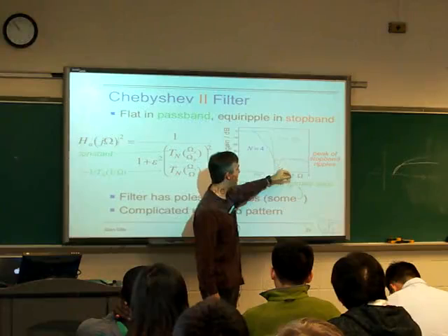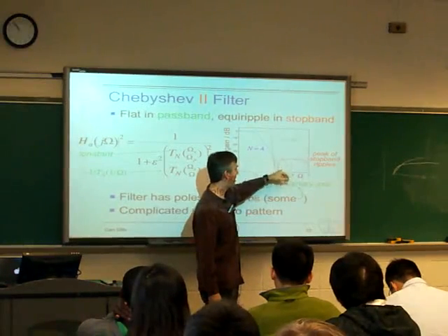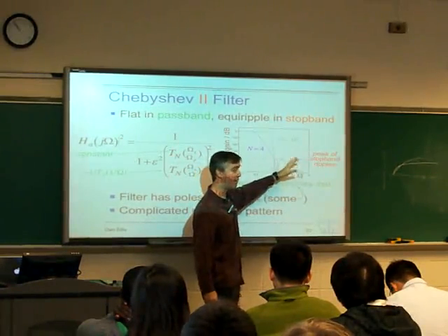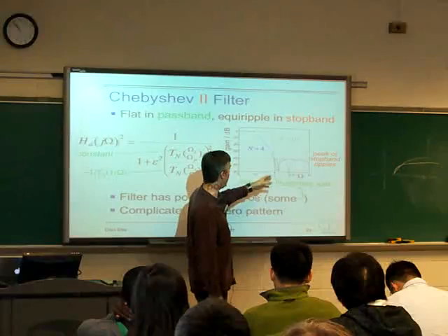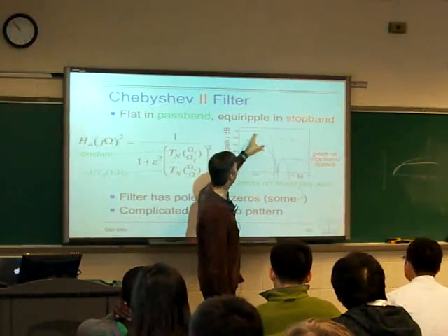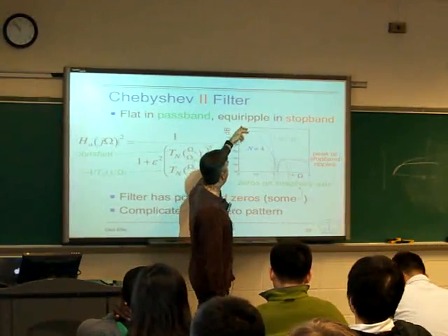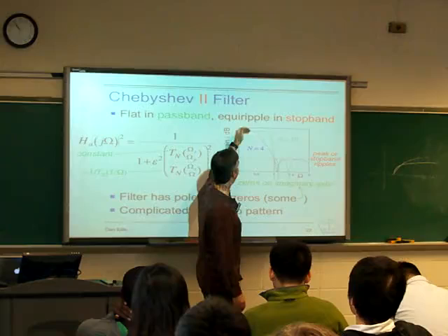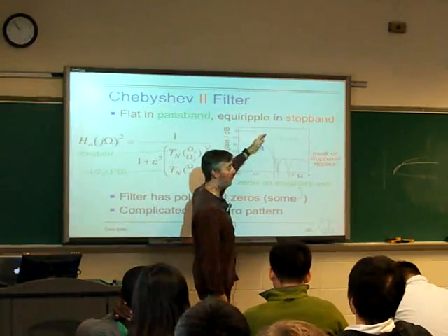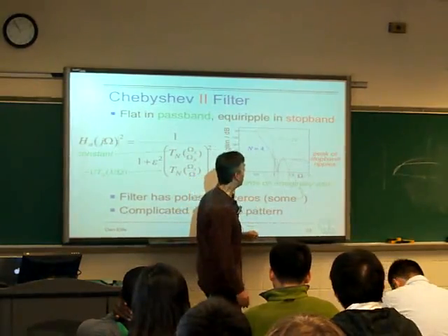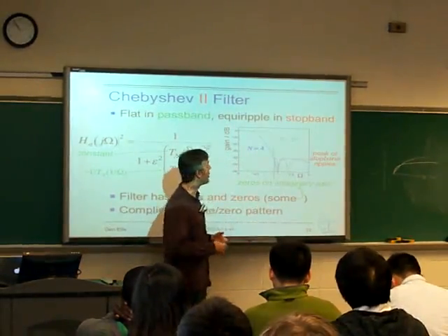The gain in the stopband is going to alternate between 0 at these points here and some maximum. We're going to choose the maximum. And once we've chosen that, we can set some criteria on how far we let the passband go down and how wide we want the transition band to be, and we can control those through the order of the filter.